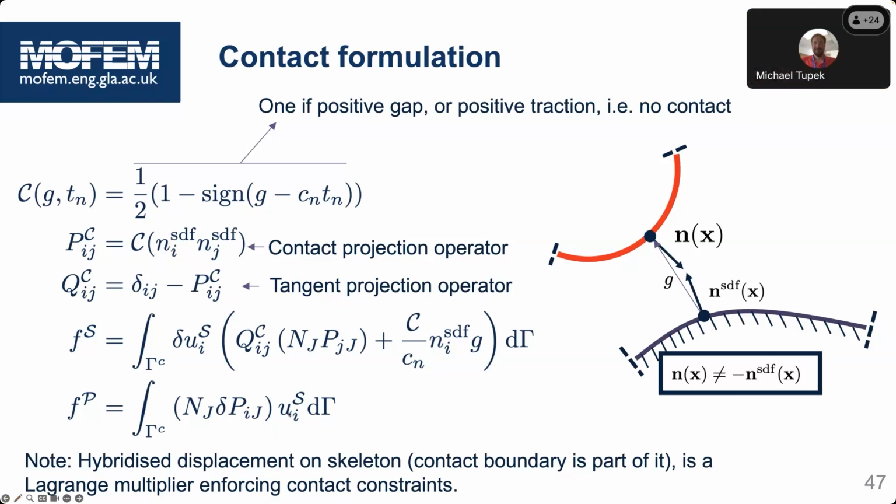And then look, if I put U bar over here, the displacement which I want to prescribe, I will enforce that displacement on the deformation. So by setting that value to the value which I want to have, I will enforce the displacement on the boundary in the weak sense. Not, I don't say penalty, in the weak sense. I get it. I guess how you enforce them.